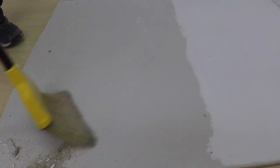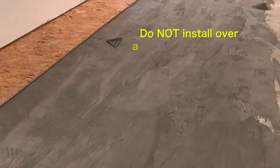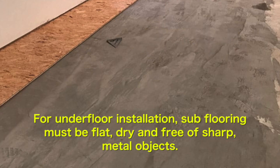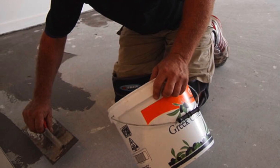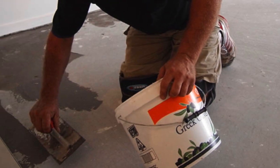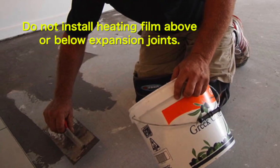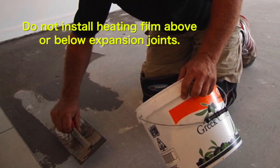For ceiling installation, ensure that the surface is flat, dry, and smooth. Do not install over any texturing finishes. For underfloor installations, ensure that the subflooring is flat, dry, and free of any sharp metal objects that may penetrate heat film. In certain circumstances, the surface may need to be evened out beforehand with plaster or level compound. Do not install heating film above or below expansion joints.